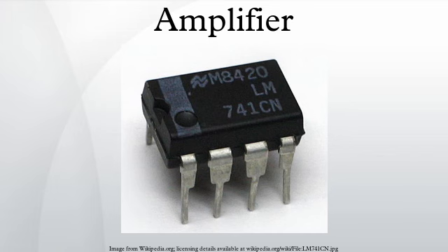Because the combined current through both transistors is mostly in the first harmonic, it looks like a sine. That means that in the middle of the square the maximum of current is to flow, so it may make sense to have a dip in the square, or in other words to allow some overswing of the voltage square wave. A Class F load network by definition has to transmit below a cutoff frequency and reflect above. Any frequency lying below the cutoff and having its second harmonic above the cutoff can be amplified, that is an octave bandwidth. On the other hand, an inductive capacitive series circuit with a large inductance and a tunable capacitance may be simpler to implement.